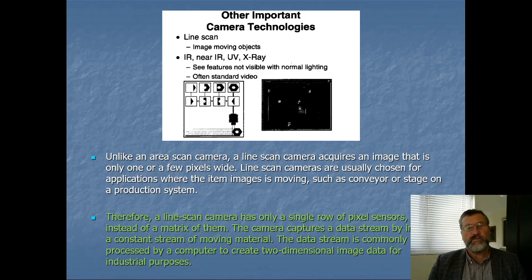I've been looking recently at some very high-speed document scanning capabilities. I bought these cameras, which are coming from Canada, and they're capable of 200,000 lines a second. Each line is up to 8,000 pixels long. So you can imagine you can get some pretty massive amounts of data coming off this technology. And it works especially well if you're trying to image things that are continuously coming along a conveyor, because it works better than an area scan, really, because with area scan, you get distortions up towards the corners of the image.